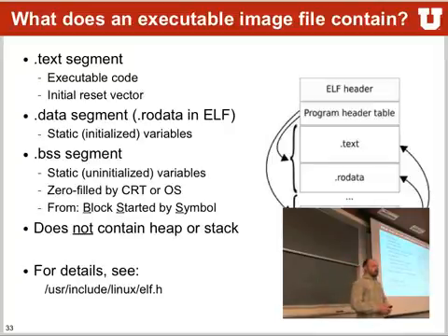The key to this is also that it does not include a heap or a stack, because that's usually sitting in RAM, and you have to make sure that whatever is in the BSS section does not collide with your stack itself.